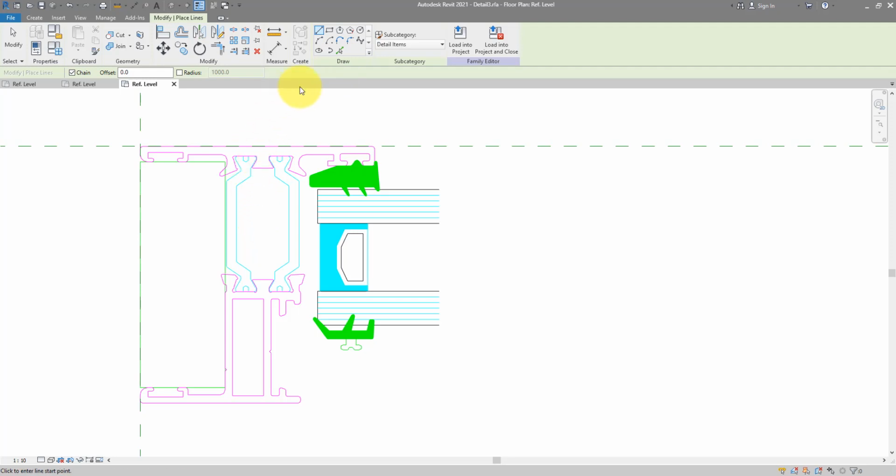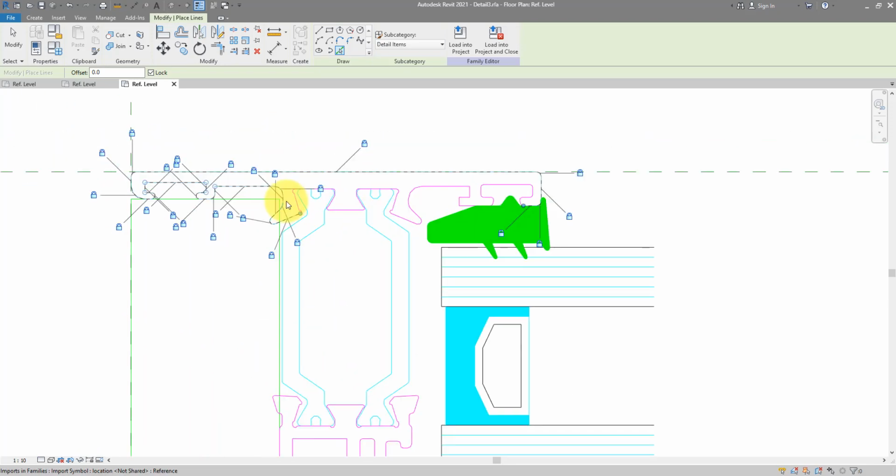The easiest way is this. Go to the Pick tool there. Hover over one of your line segments and then press Tab until the whole chain lights up. Here we go. You can see there that the Tab doesn't include the whole chain of lines for me. If I click now, you will see clearly why. Just click. And you can see the black lines, they start from here, going all the way around this corner as well. But then it stops here.